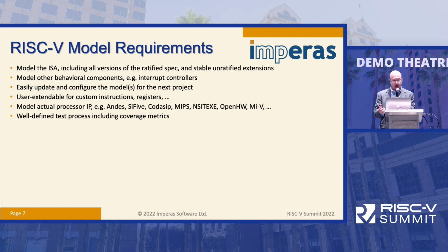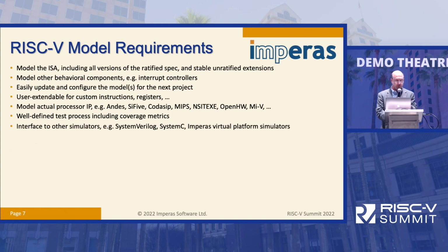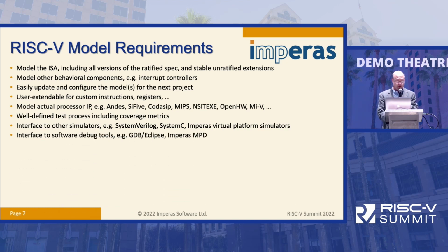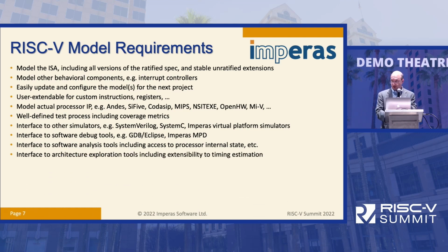There needs to be a well-defined test process, including coverage metrics. That's a well-defined test of the model itself. We actually run, I think, something like 17,000 tests when we do code check-in on the models. Needs to be able to interface to other simulators, SystemVerilog, SystemC, the Imperas Virtual Platform Simulator. Needs to be able to interface to software debug tools, software analysis tools, and architecture exploration tools.